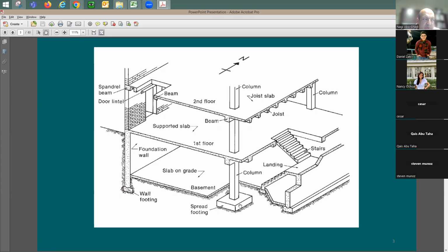So when you size the footing, you need to be sure that the contact pressure between the soil and the footing is going to be within the allowed value of the soil, not the concrete, because the concrete is going to be strong. So the bearing pressure on the concrete coming from the soil is going to be easy to be handled by the concrete. The whole problem here is going to be in the soil.